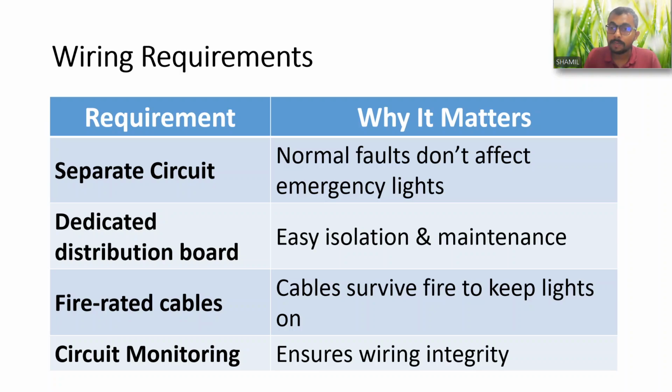The reason we need fire rated cables is to survive the fire and keep the lights on. And the last one is that the circuit is monitored to ensure wiring integrity. This particular requirement is there in the centralized battery system. Okay, so these are the wiring requirements.